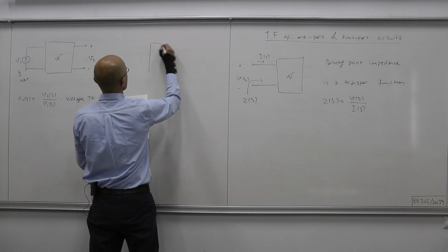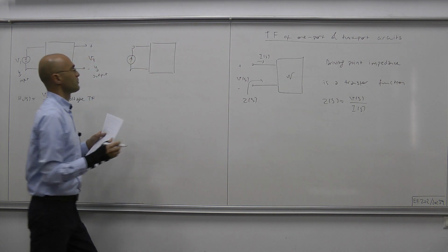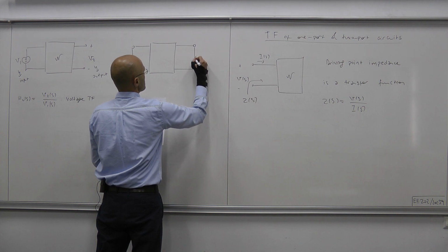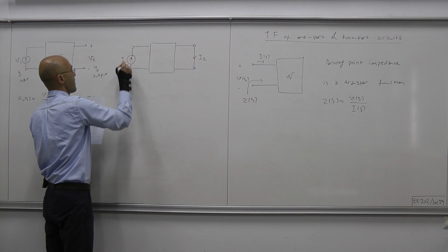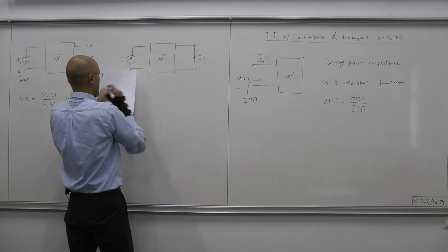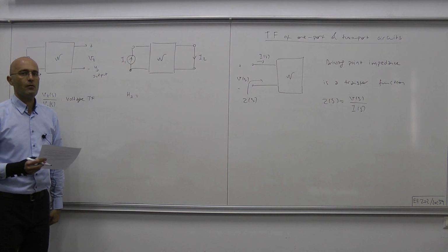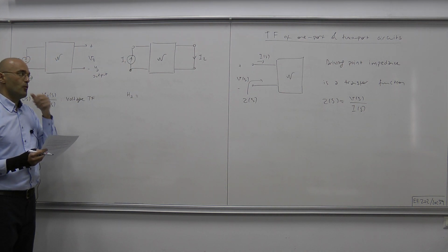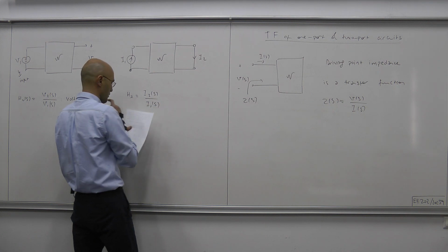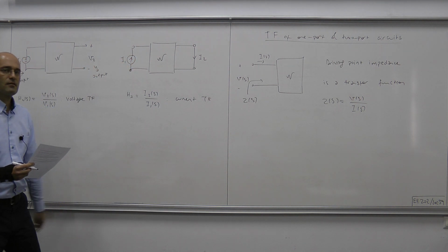Okay, and then we can talk about the dual case where we have input entering from the first port, and then the second port is shorted, and I2, the current flowing through that wire, is our output. Okay, and then we have the transfer function as I2 over I1, and that's called the current transfer function for the through port. I2 of S over I1 of S.